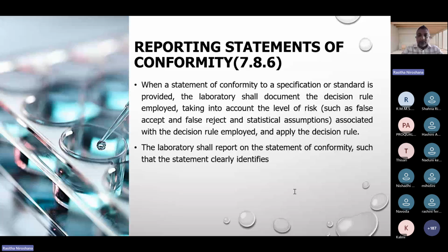So whenever you take a reading, for example 7, try to understand this very carefully: your pH reading is 7, but it actually indicates 7.2 pH. You got my point, right? When you do the calibration, it said a plus 0.2 error is there. So when you do the testing, your pH reads 7, but actually it is pH 7.2. I hope you got my point.